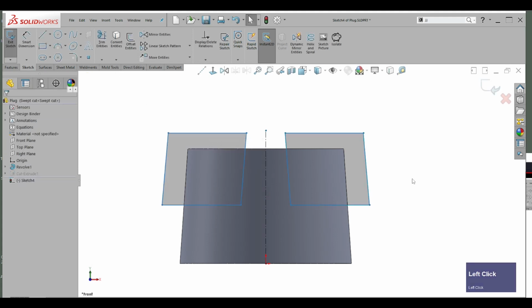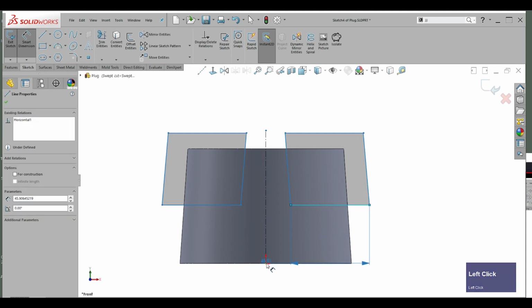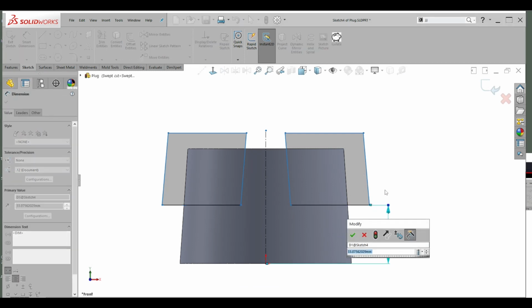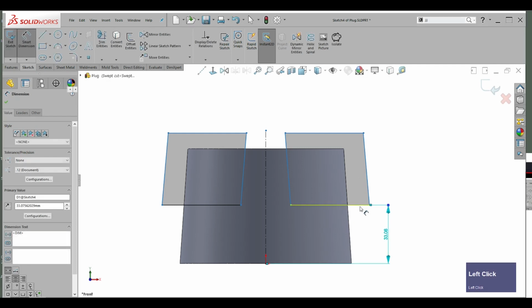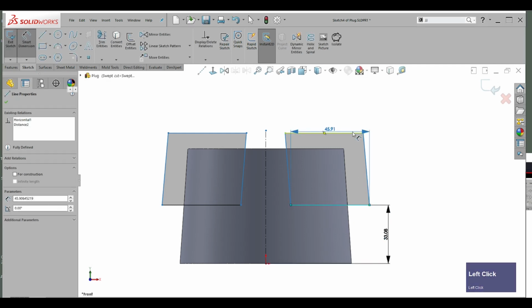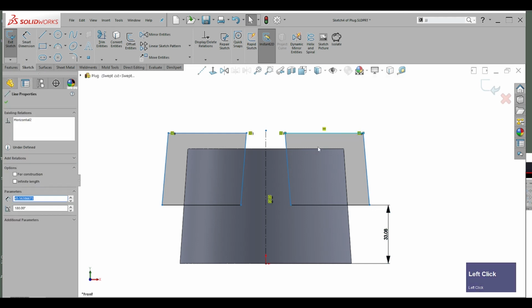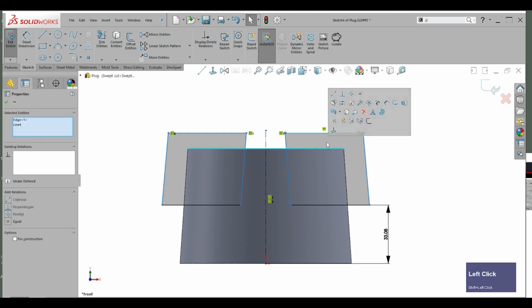Okay. And then let's just put some basic dimensions in first, and then I'll explain that little bit about not having this as a horizontal piece. Right, I'm going to leave that one off. I think I showed you in class that you could associate a line with a feature or part of a feature. So I want those to be collinear.